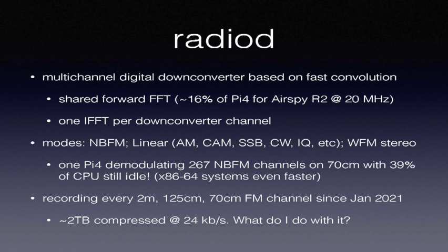Functionally, it's what's called a digital down converter, or DDC. Usually this function is done on a field programmable gate array. Most SDRs do it this way. I set out to show how much can be done without using an FPGA. Everything runs on a general purpose computer.